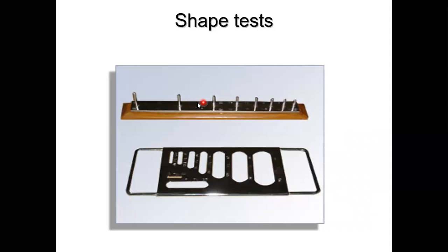This is for the elongation index, where we are going to see the length of the aggregates. Here it is the thickness of the aggregate, that's why it is called the thickness index. Here you are going to see the length of the aggregate, that's why it is called the length index or elongation index. Length gauge, thickness gauge.